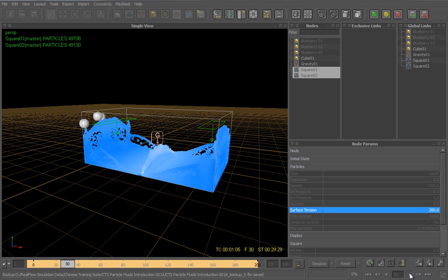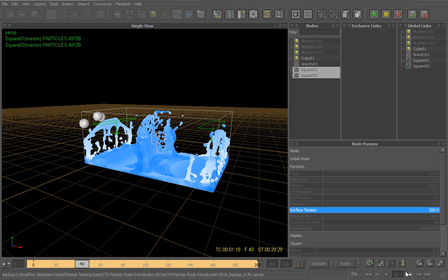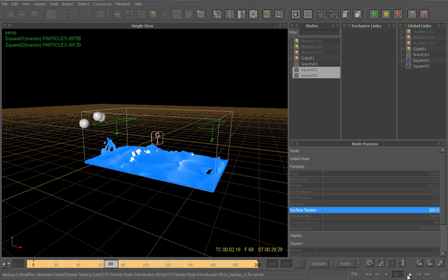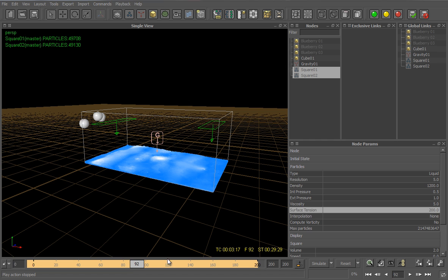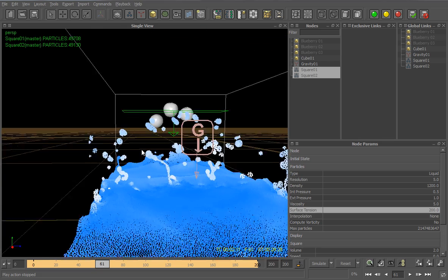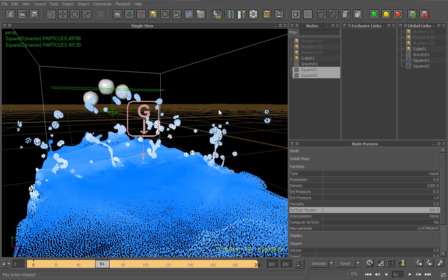As you can see, the fluid forms nice drops. There are also splashes, but the fluid does not break apart into tiny droplets. We also have a smooth surface, and our virtual milk has the right velocity, not too fast, not too slow. All in all, we can use the adjusted parameters, but you can also experiment with other settings, for example, higher surface tension.